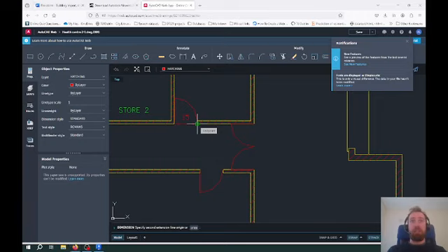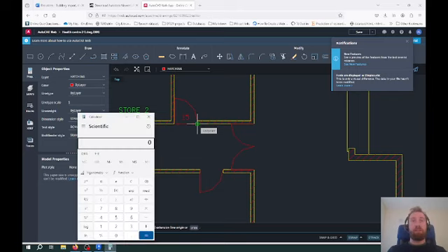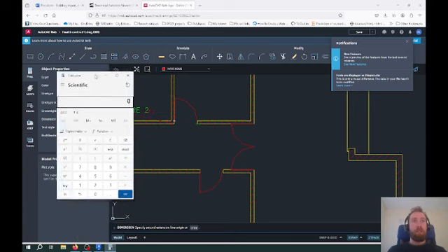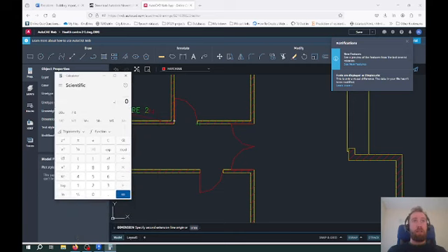An easy way to do that is to work it out based off a known dimension and the dimensions that you're importing from. So I have a calculator up here at the moment. We know that a door is typically 900 millimeters. And if it's represented as 15 units in our CAD drawing, we have to scale that by 60 units in order to have it imported into Revit correctly. So just on that short calculation there.